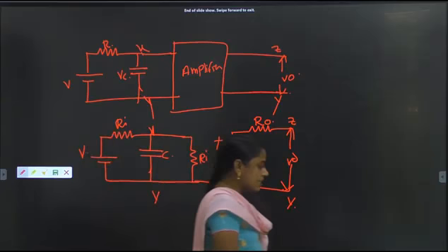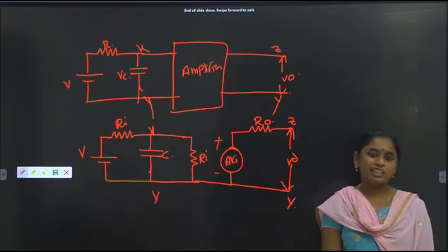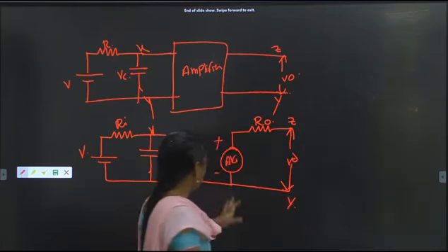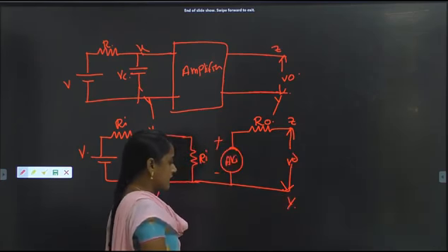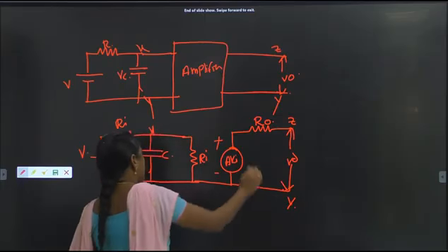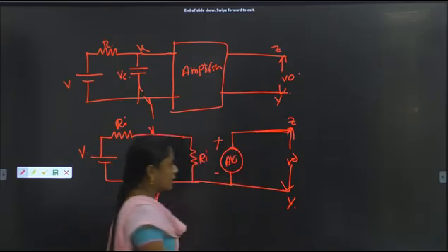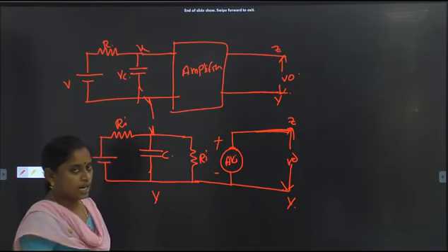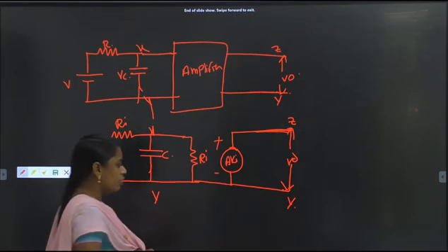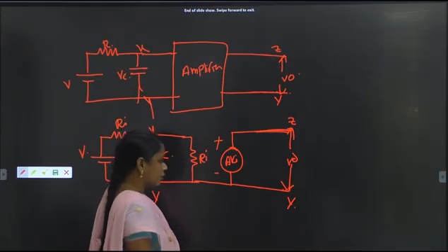Here the transistor is an emitter follower circuit. For the emitter follower circuit, the gain of the amplifier will be 1, and this R0 can be replaced with a short switch. So I have to redraw this circuit replacing R0, because R0 will be short circuit. The resistor can be replaced with a short switch. That's why the circuit will be like this.